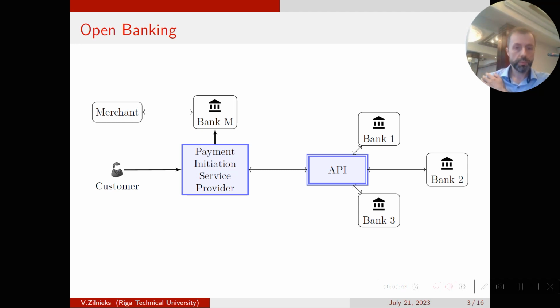In this case, the heat exchange with the indoor environment is done through a manifold-based distribution system where the heating emitters are fan coils. Well, the wall is made of different layers, so we have different resistance, different capacity, and we will consider the boundary condition of the third kind on both the exposed surface.